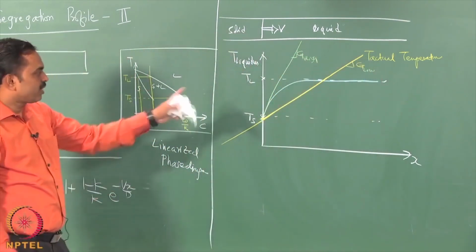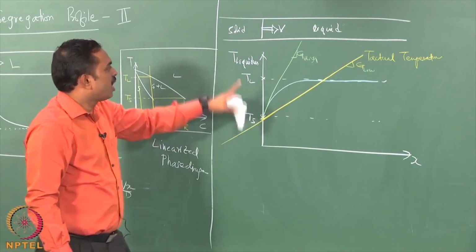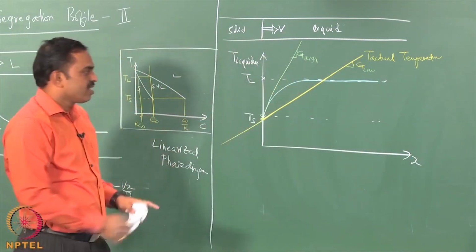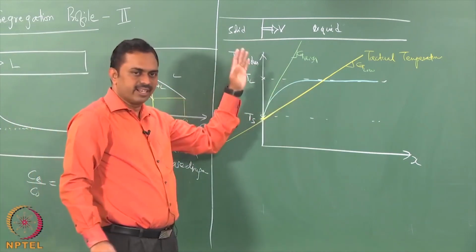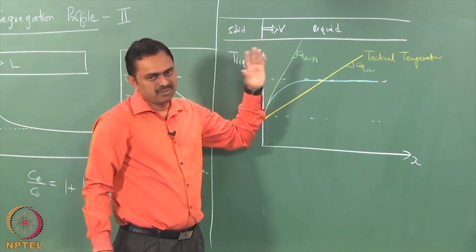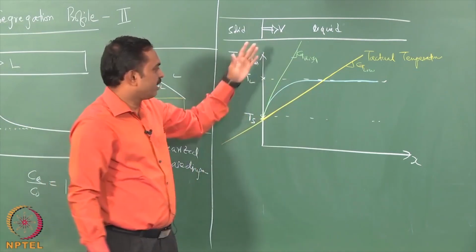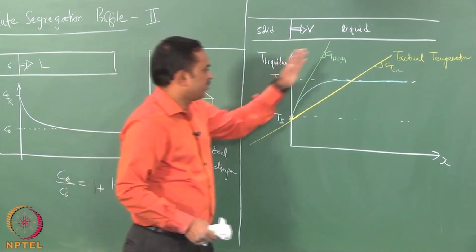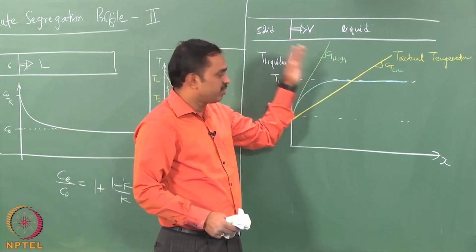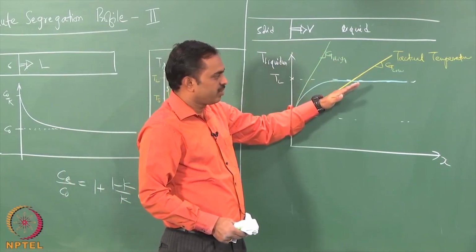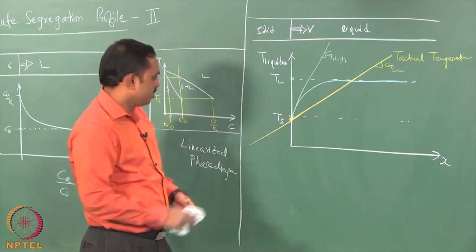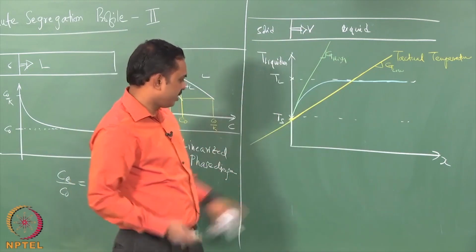Okay. Now, we can inspect what would be the effect on this solidification mode by looking at these two profiles when we have a low gradient and high gradient. What we mean by high gradient is situations like laser welding, electron beam welding. Low gradient we mean situations like gas tungsten arc welding or manual arc welding. Okay. So, if you change the heat source intensity, temperature gradients are changed from shallow to narrow, and therefore, how you can look at the interface is something that we can do now.